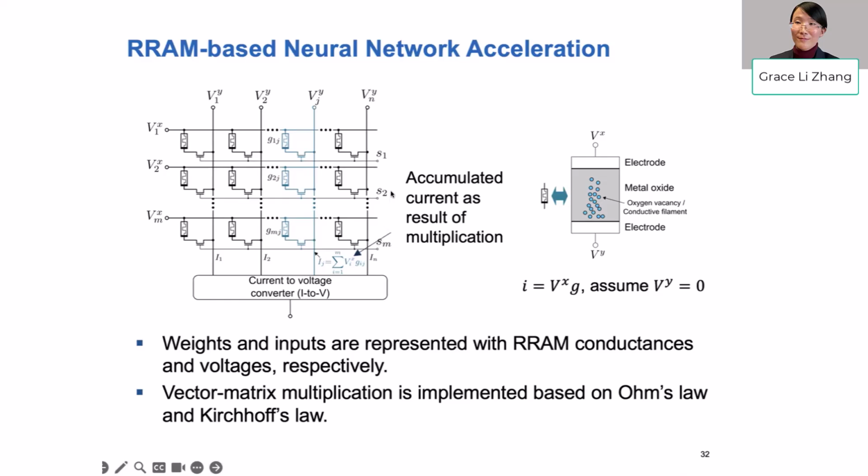It's not very advanced because if you manufacture such devices with very advanced technology, the yield is very low. There are a lot of faults and variations, so they are not stable if you manufacture at large scale. Even if you use older technologies, they also suffer from variations, noise and programming problems. So the device is a big problem for analog in-memory computing.